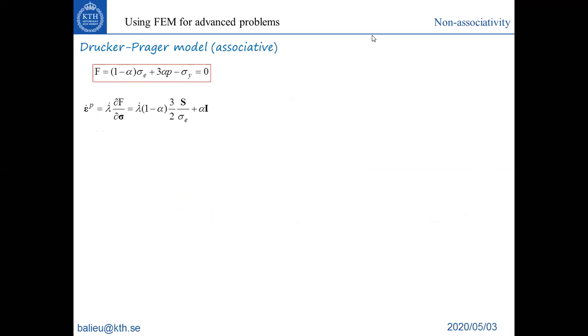I mean all the materials which have a pressure-sensitive yield surface. That means it can be asphalt concrete, it can be soil material, it can be polymer material. There are many materials. And all these materials which have a pressure sensitivity also have an increase of volume due to the plasticity. So to be able to model this increase of volume, you need to use this criterion.